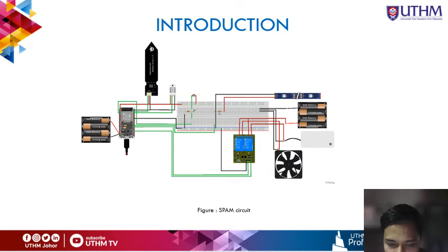The capacitive sensor will work together with the DC water pump. When the moisture does not reach a certain threshold, it will trigger the pump to pump water toward the dripping system. The DHT22 will send humidity and temperature, and its feedback is the cooling fan. The cooling fan will turn on when the air is dry or the temperature is high.